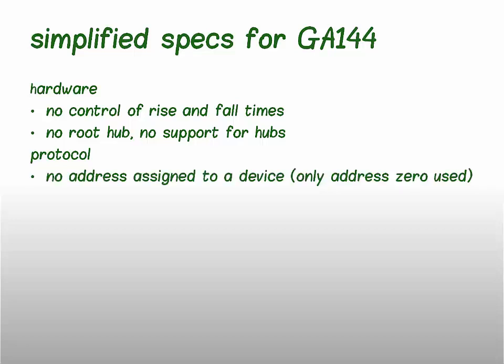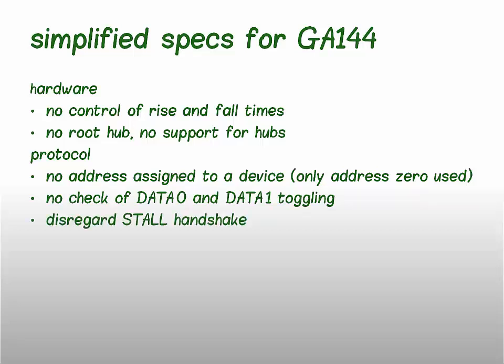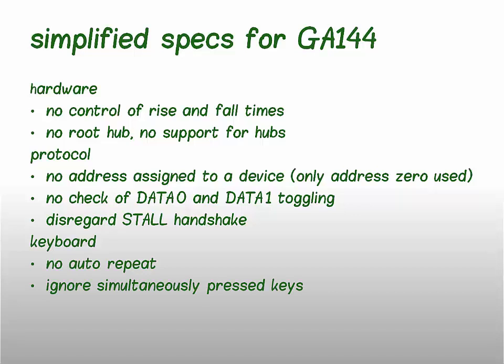Also, we never transfer more than 8 bytes of data in a single transaction. Thus, data 0 and data 1 toggling is not checked. We also disregard stall handshake. Finally, the keyboard controller does not provide for auto-repeat feature, and it also ignores simultaneously pressed keys except for Shift key. Let's have a look now at the hardware part of the project.